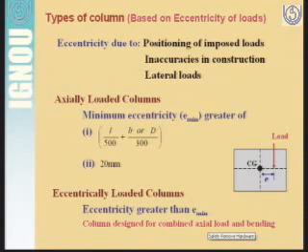For getting the effective length, the code describes two graphs as well as a table. In the table, ratios of the effective length are given based on the boundary conditions of the two ends of the column. By applying those ratios, you can get the effective length from the unsupported length. That way you can calculate the effective length of the column very easily.